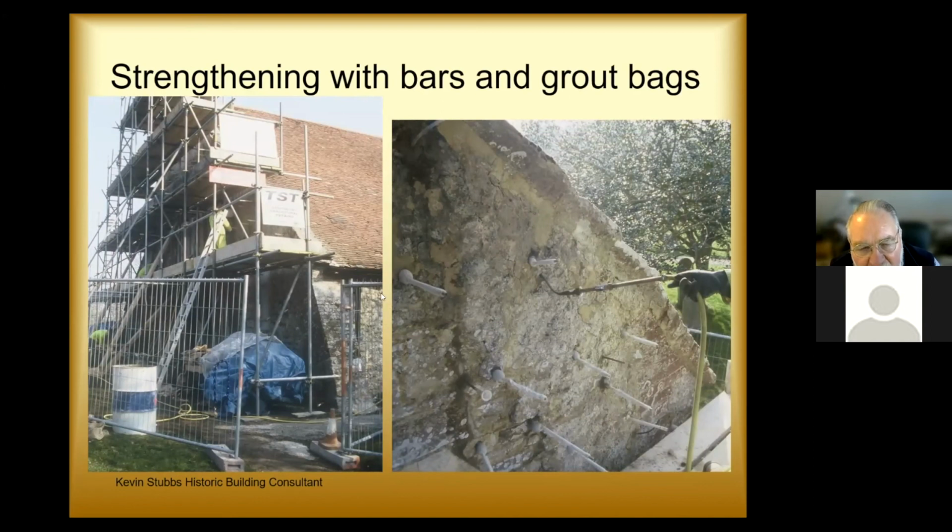And it's an aisle building, and so the last two bays of the nave arcade, the arches, were beginning to spread as the whole building started to try and move westwards. So what one needed to do was tie the whole lot back together. And this was done using a modern method of anchors and grout, the Cintec method, where they've drilled